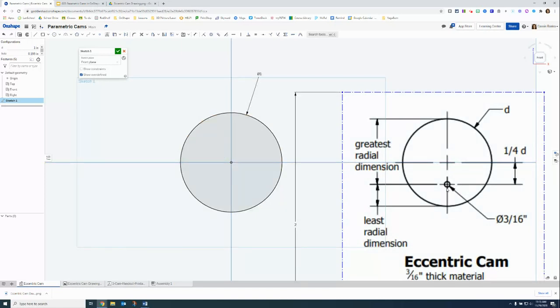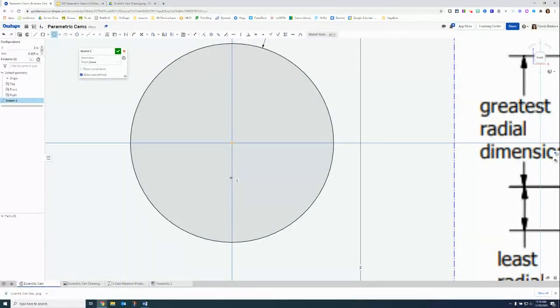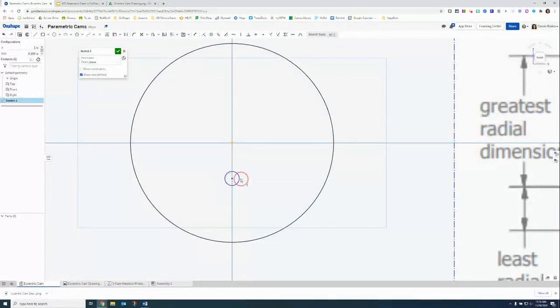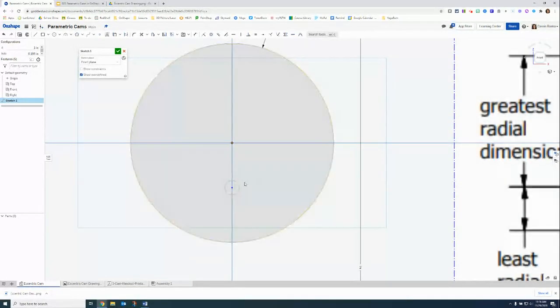Now I'm going to put in the hole for the axle. So I'm going to do C for center, and I want it to line up with the origin but not actually be on the origin. If you zoom in, you can see that yellow dotted line and the vertical constraint that pops up. So if I go ahead and draw my circle, they are constrained on this line, so I can't drag it either way. That red circle that you see is actually my cursor in Screencastify, but I can drag my circle up and down. So it's constrained horizontally or vertically.